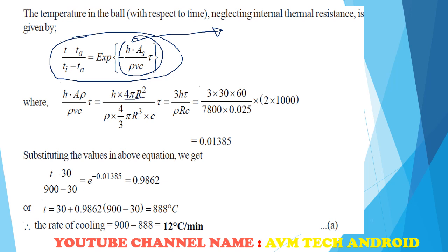As is the surface area. For a ball, volume is 4 by 3 pi r cube and surface area is 4 pi r square. So we will get 3h tau divided by rho r c.